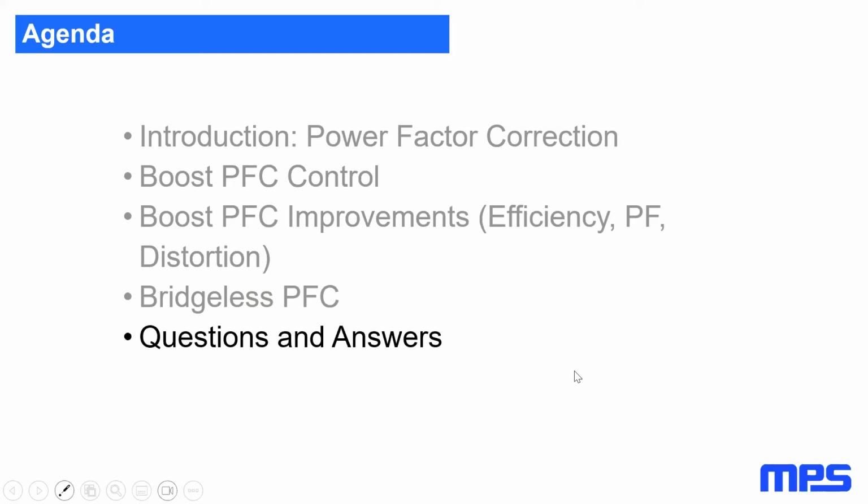Just that already will increase the price. So it will depend, of course, on the selection of the type of switches, if it's GaN or silicon or SiC. But I couldn't give you even an approximate price for totem pole, maybe 30%, but this is just a guess. So yeah, I don't have an exact answer for that.